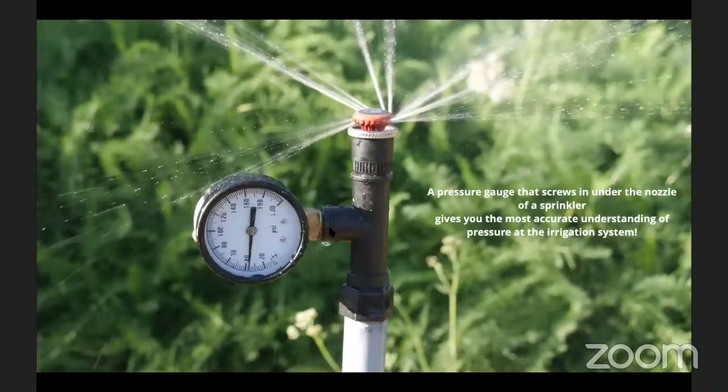This is a picture from after I did all the pressure regulation, set up my irrigation system, and tested. On this system, I was just below 40 PSI, which was the perfect range for this sprinkler.